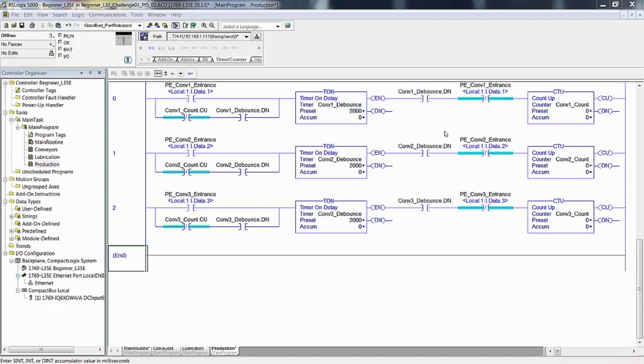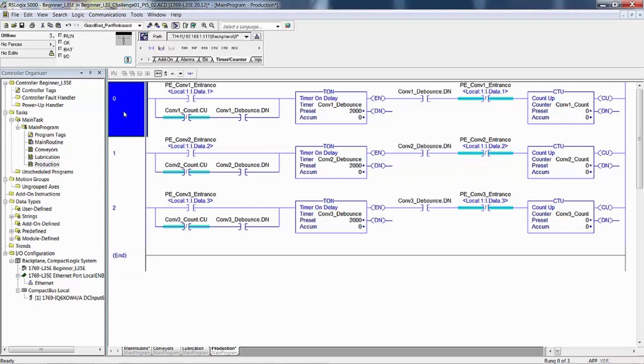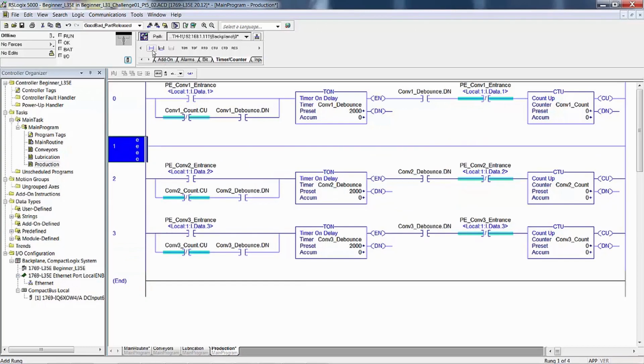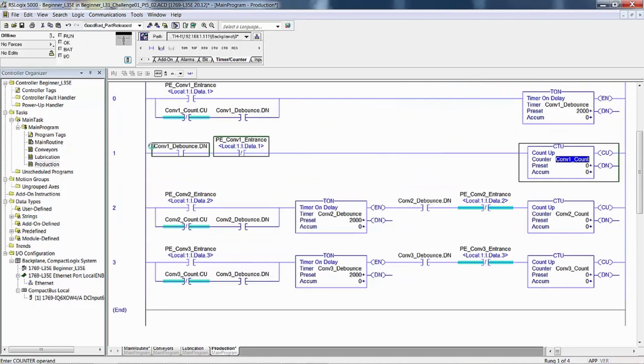Now, traditionally, if this were a 500 or RSLogix, it would look like this. I'll just go ahead and do this real quick, just for grins. Let's grab this, and this. Drag it down here. Because you can't put output type or execution things like timers and counter instructions in series in the 500.